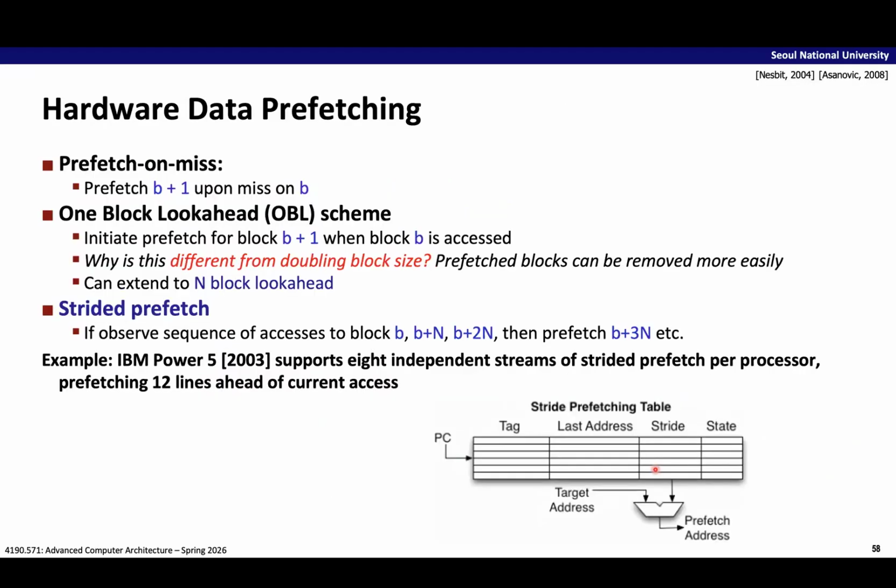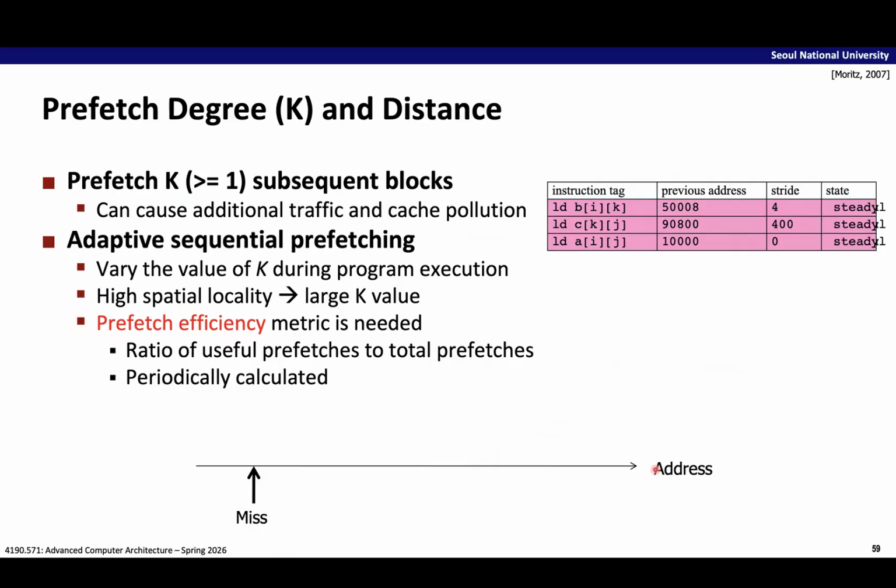And we also studied prefetching. In case of cache miss, we need to access memory or larger cache. But by checking the memory access pattern, we can initiate prefetching operation. To do that, we use two terms: prefetch degree, the number of cache blocks prefetched, and the distance, the address distance between fetched cache blocks.